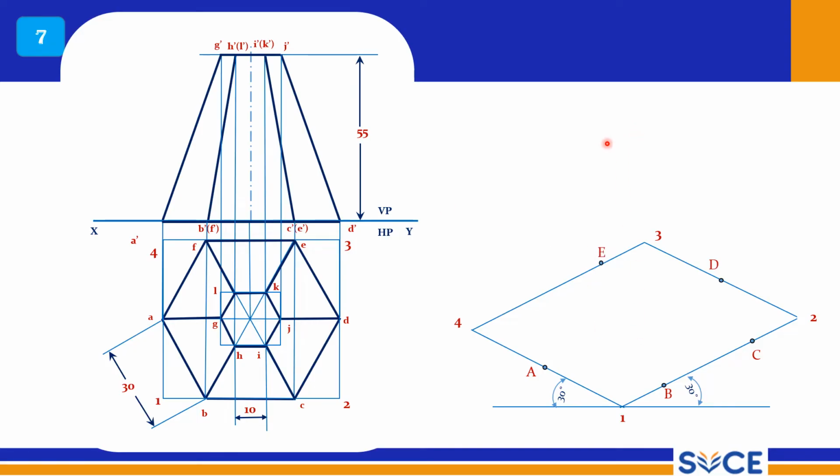From this center, you project up with this height, 55 mm. So now this point is the center. Now measure this distance as well as this distance, and you can draw those two lines parallel to the 30-30 line, right? You can draw a line here, and that is this line, and this line is nothing but this line. So this vertical line G to J is this distance, and from here to here this distance. Now you draw parallel lines and complete this rectangle on top.